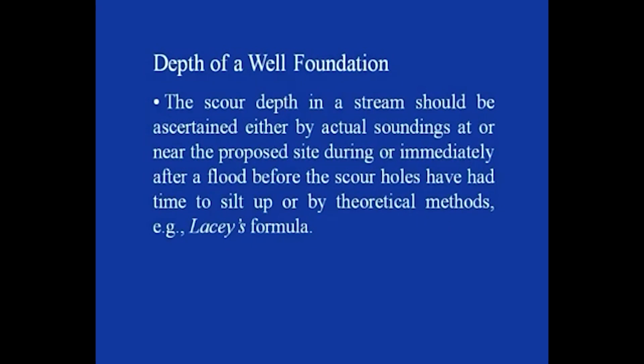The scour depth in a stream should be ascertained either by actual sounding at or near the proposed site during or immediately after the flood, before the scour holes have had time to silt up, or by theoretical methods, that is Lacey's formula.